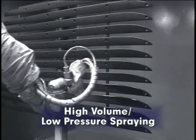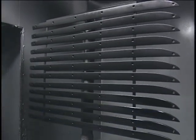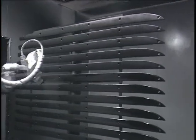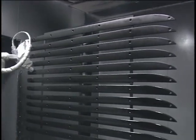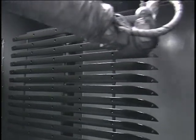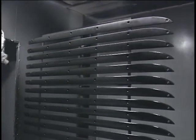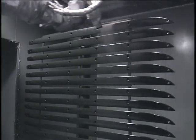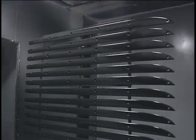High-volume, low-pressure, or HVLP spraying is an air atomization system that uses less than 10 psi, or 69 kilopascals of air pressure to apply paint. HVLP spraying produces a softer, more controllable spray, reducing overspray and paint wastage.